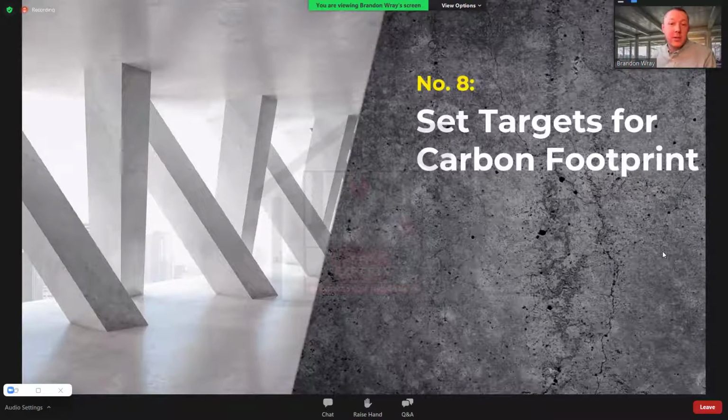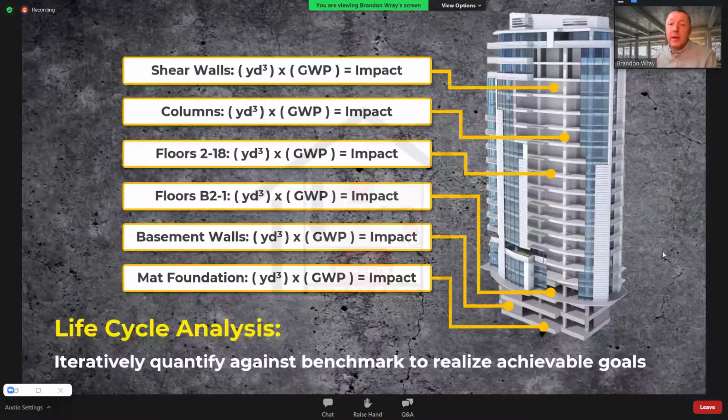The best option is building life cycle assessment to set a carbon budget for all concrete on the building. Many concrete companies have published EPDs, environmental product declarations for concrete, and most would be willing to publish EPDs specifically for a project if needed. NRMCA has published a cradle-to-gate life cycle assessment for ready-mix concrete report, which does have an industry-wide EPD associated with it. So armed with this information, you can conduct an LCA to determine the embodied impacts of concrete of a benchmark building using typical concrete mixes with typical amounts of SCMs as compared to a proposed building concrete